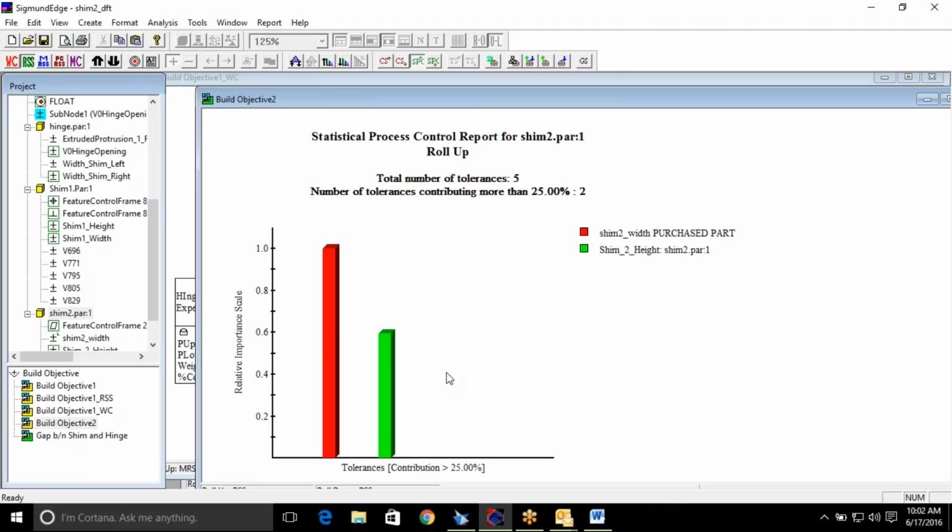So this is where I can justify spending more money if I have to. This is where I can justify having them put on a CMM queue and taking variable data. These are also areas where you can ask your manufacturing to have a better control. They'll come back and say, okay, that's an extra hit, extra gate, an extra machining step, something that will cost you money.